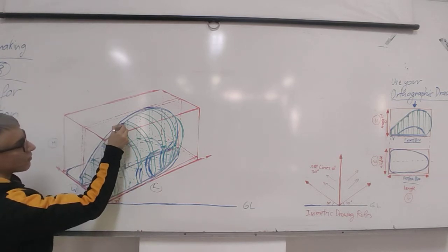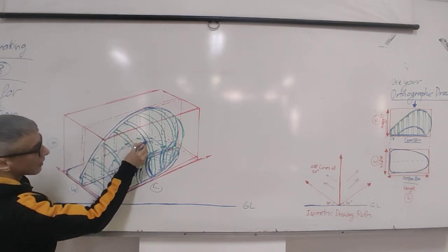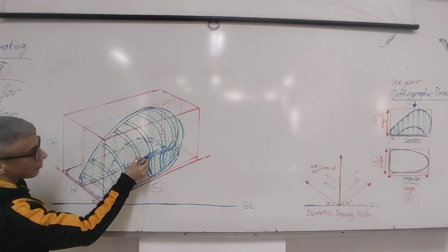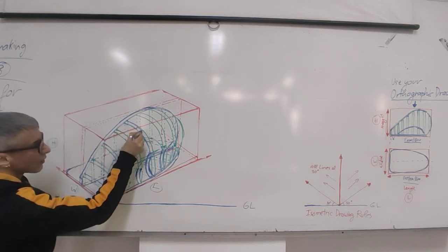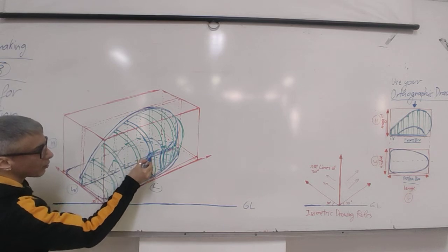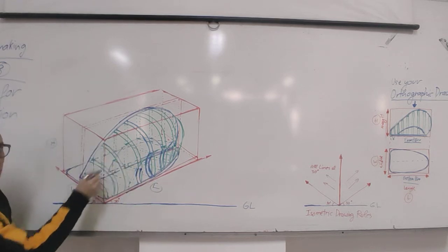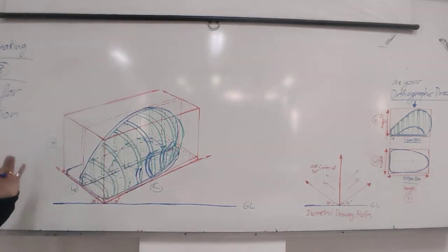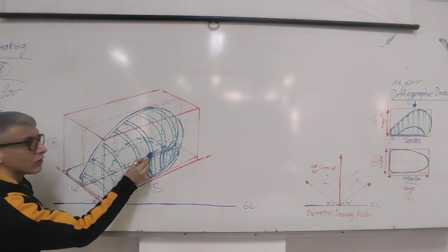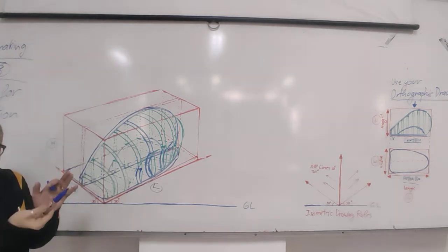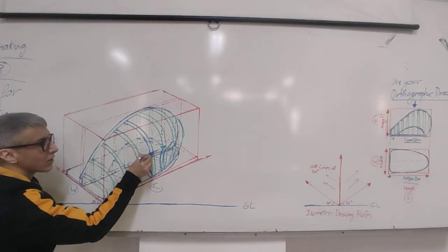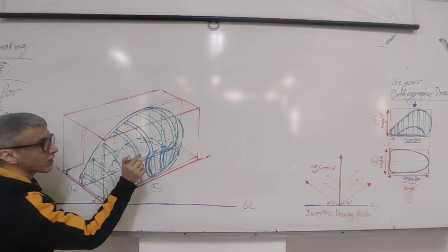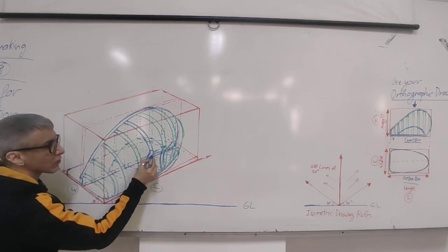So we have lines that suddenly change the shape here at this point, okay? This is 2 millimeter thick cardboard, the same thing with all the lines. Now, we look at the model, we look at our drawing, and we say, okay, is this here a corner or a radius? If it's a radius, you need to indicate the start and end point of the radius, remove this line, and draw 2 lines.